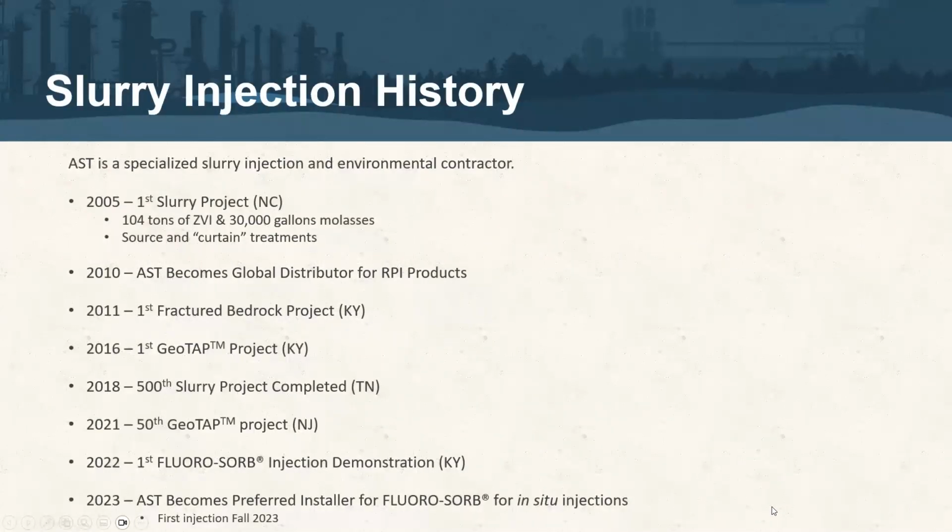So just briefly, Fluoro-Sorb will have to be installed in situ via injection as a true slurry. And so when it comes to slurry injection, the design, the equipment, the assumptions, the planning even changes drastically versus most other in situ injection projects that you're used to. The slurry we're talking about here today will be injected via DPT points. So these are not injection wells. Most slurries that we deal with are not good to use standalone permanent installations for injection.